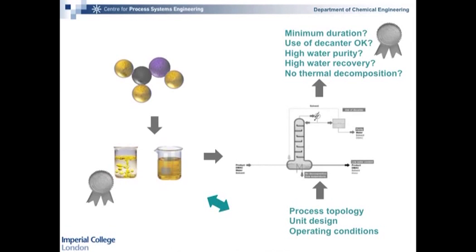And this can be, for example, whether you have phase separation or not. Okay, and this will be affected by the molecules that you change. And here you have, in fact, one of the first examples of what I mean by best behavior, which will crop up during the talk. What you find is that for a given temperature and pressure, the mixture is going to find itself in the configuration that minimizes its Gibbs free energy. And so this is its best behavior. Whether it separates into two phases or is in a single phase will depend on trying to reach this minimum. And we'll see that it's very important to be able to solve this problem in order to solve the overall molecular and process design problem.